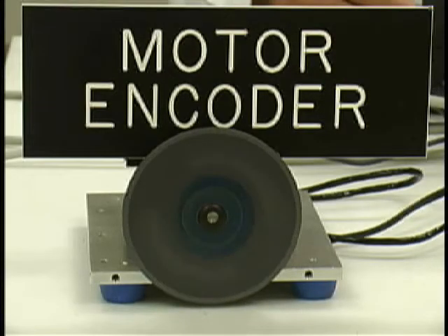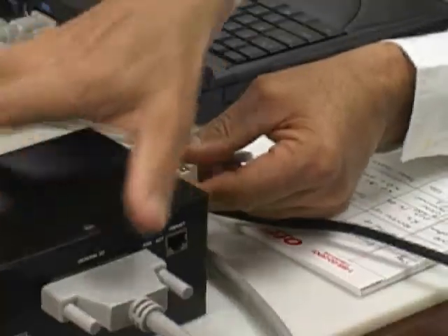Now, the whole operation at this point is executed from the motion controller. The host is not involved. As a matter of fact, I could disconnect the host altogether. Notice that I pulled the plug on the RS-232 and the operation continues. Now I could put it back. Such an operation is known as standalone because the controller could handle the whole motion and we don't need a host computer. There are many applications where people would prefer to use this mode either for cost saving to save on the computer or for environmental reasons, they don't want to have a computer in the shop. But generating motion, while this is nice, it's not the end of the road.